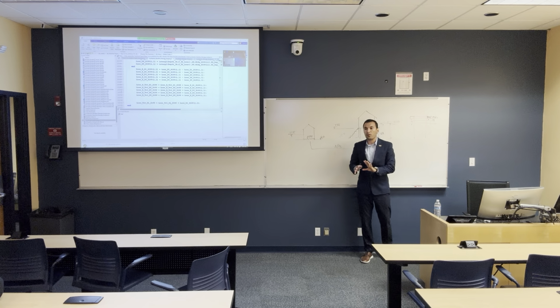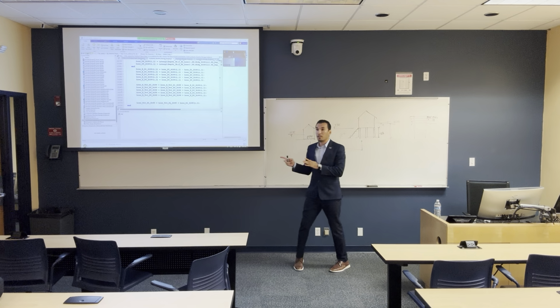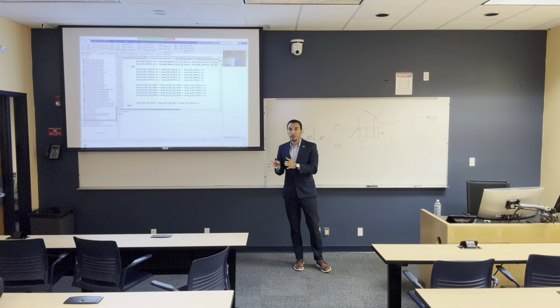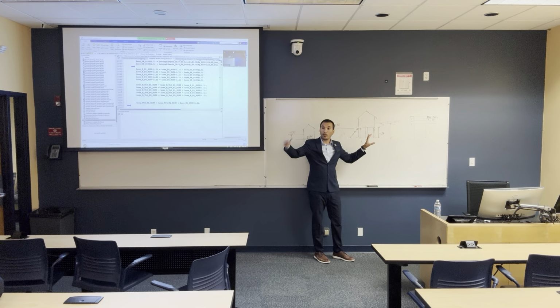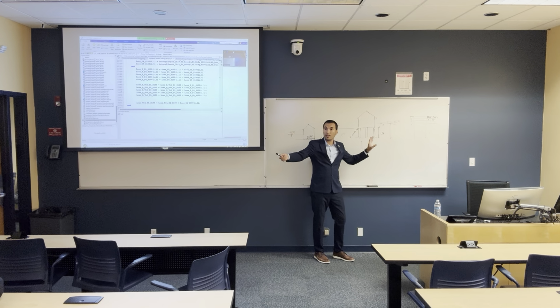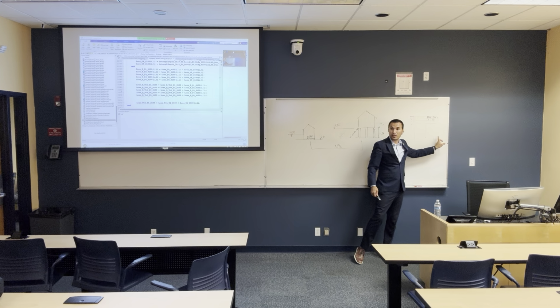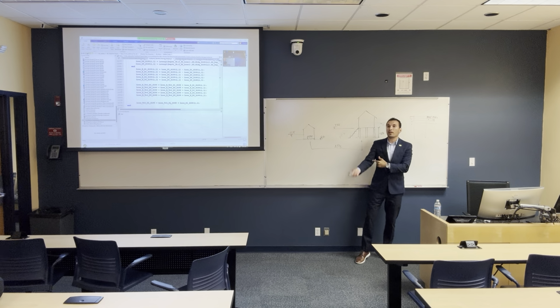And if I want to model it for just a few buildings, or 10% of the buildings, you select the 10%, you have the new foundation height, let's say it's 12 foot, and you add 12 foot to the old elevation, so you are going to have a new first floor elevation, and you rerun the code.